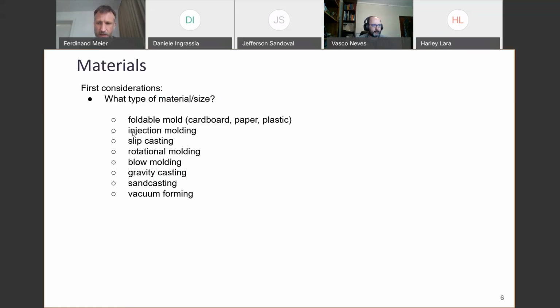The good thing about molding and casting is that all the techniques you learn, you can also use for injection molding, which is how almost all commercial plastic pieces are produced. It's a bit more complicated because for injection molding you need a steel form and you have to have draft angles, which in our case is not so important. But with this assignment you will get a sneak peek into industrial production as well.